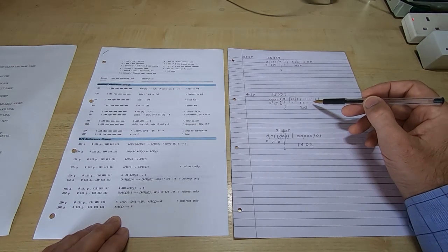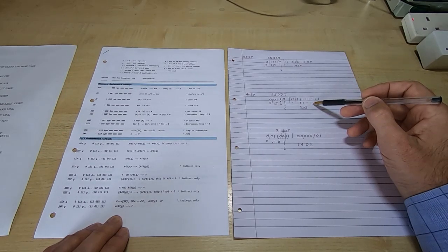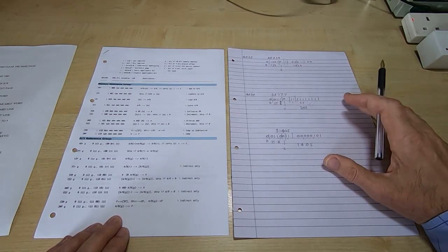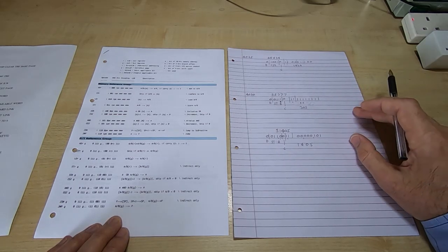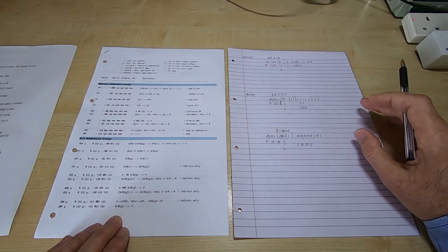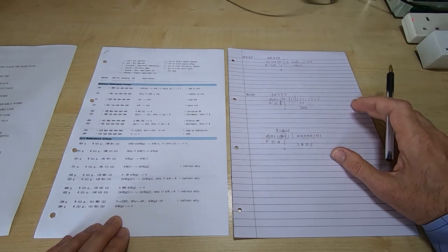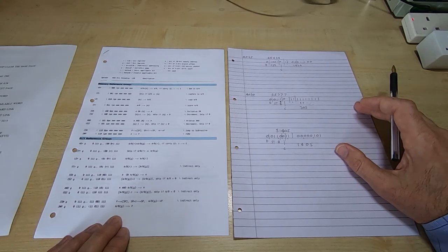And because they're mask ROMs and the code is put into them at the time of manufacture, and also they're impossible to get hold of, there's absolutely no chance I could get hold of any, even if I had a way to program them, and again the cost would be prohibitive. So if the address decoding doesn't show anything up, I have to consider this ROM board is dead. There's little value in trying to mess with it or get it working, because I do want to get the machine working, and it's not really a restoration, it's more of a repair.